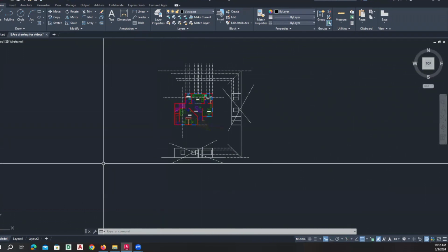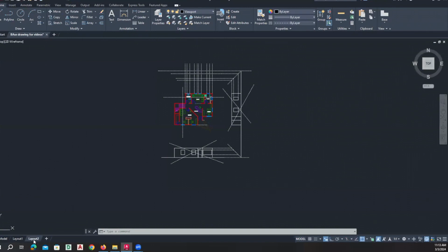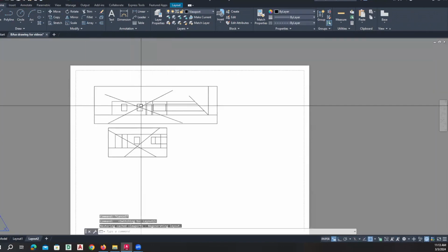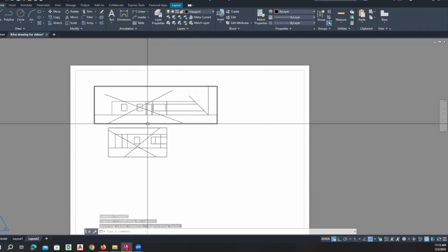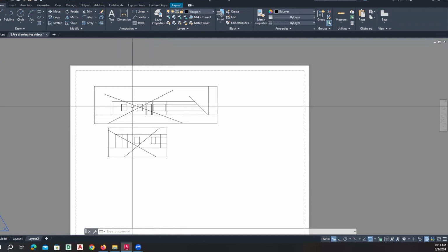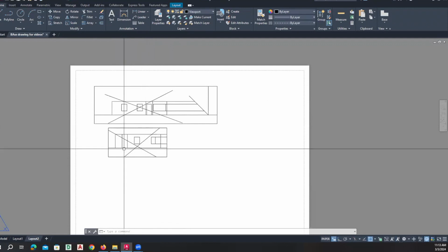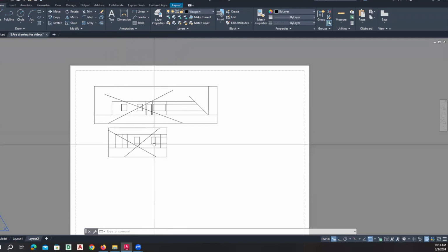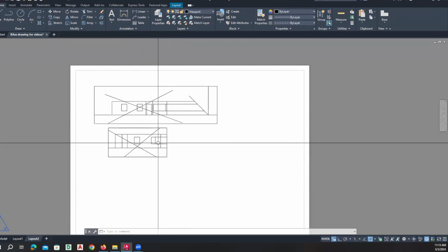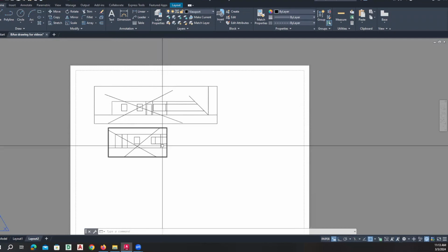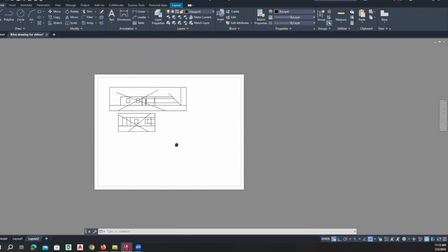Once we get those elevations drawn, we can bring those elevations into a viewport. We can rotate our UCS, orient the plan to that UCS, and then rescale the viewport so that we can fit what needs to be fit into those viewports. And you would do that around each plan so that you can see all of the elevations you need to see.